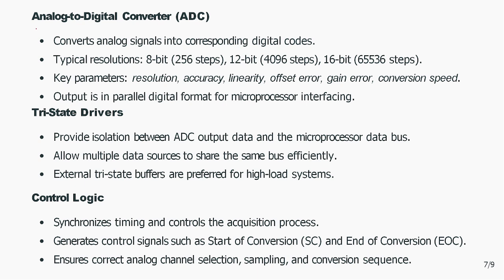After passing through the sample and hold, those samples are sent to the analog to digital converter, which is available at different resolutions. It can be an 8-bit ADC, a 12-bit ADC, or a 16-bit ADC. Depending upon the application or the required resolution, we can choose different types of analog to digital converter.